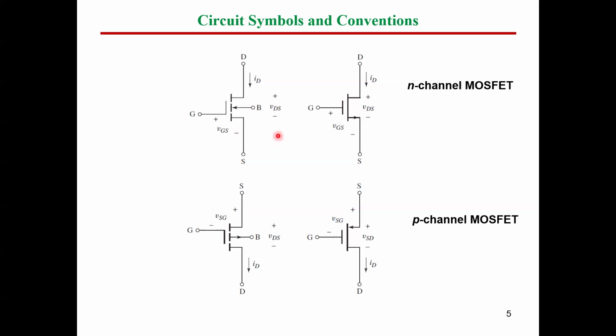So this is the nature of the MOSFET itself. This is because we have some other power electronic elements called IGBT. IGBT has no internal diode like in MOSFET, but MOSFET all of the time will have its internal diode. Okay, so this is one of the symbols of the MOSFET.